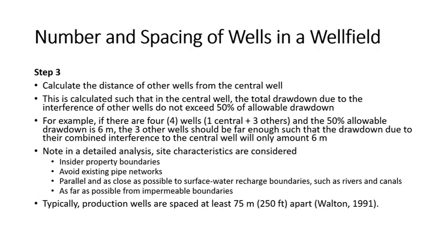note that in a detailed design analysis, other site characteristics are considered. So the wells should be inside the property boundaries. You should also avoid existing pipe networks. And typically, the wells should be as close as possible and parallel to the recharge boundaries, such as rivers and canals.